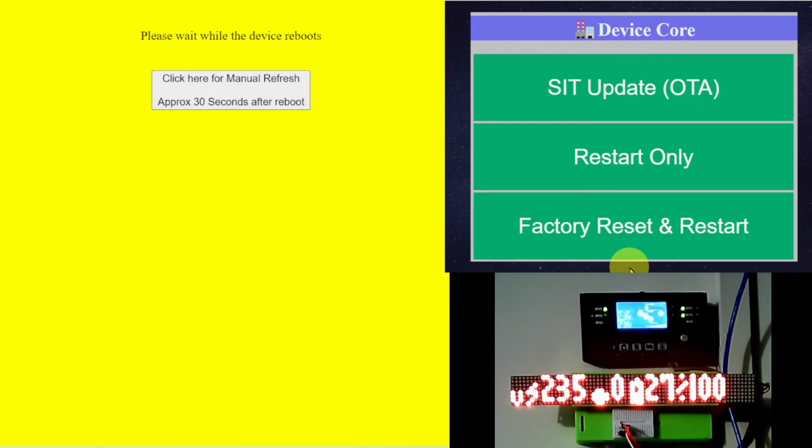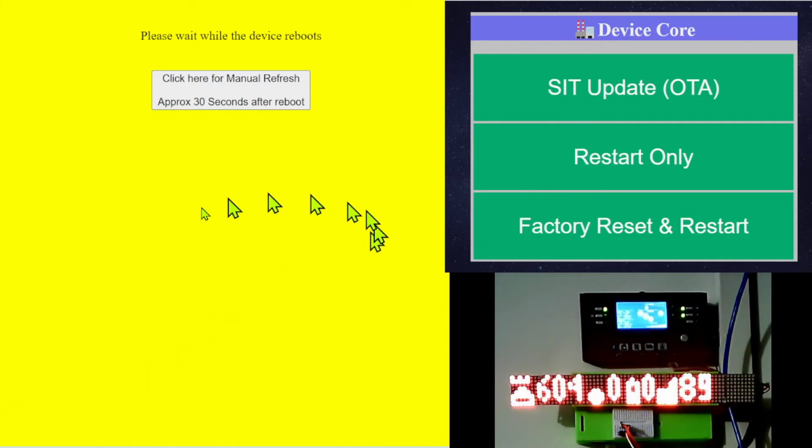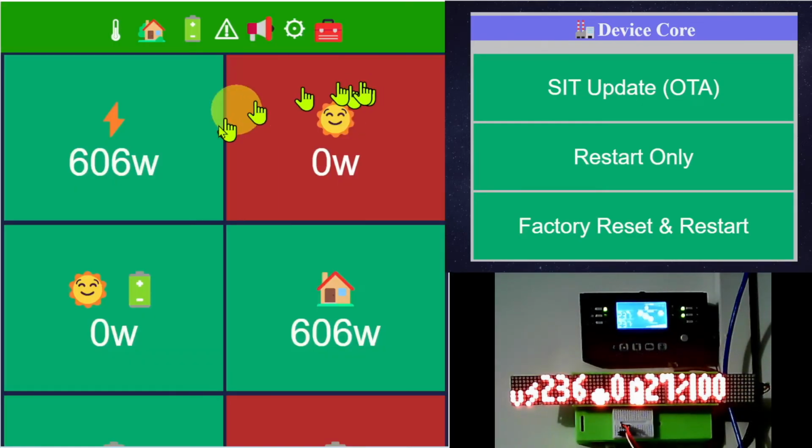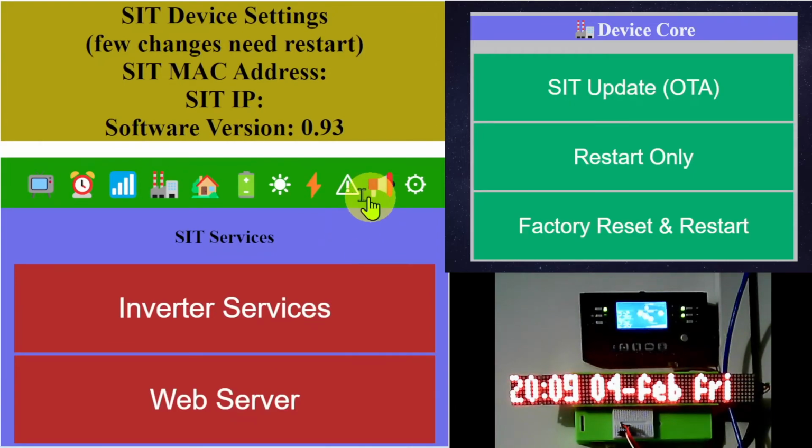If buzzer is enabled, you will hear initial setup beeps. Device will be ready in less than a minute. If the humidity and temperature sensor is enabled, then restart may take a bit longer. You can see booting status on the display too, LCD or matrix, whatever you have. Once you see numbers, this means reboot and setup is complete. Technically, the Arduino loop has started. Let's refresh the SIT web page.